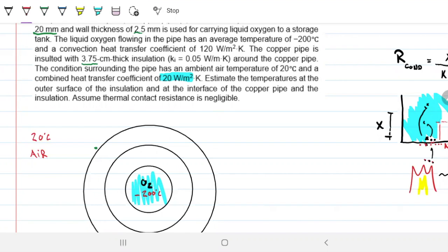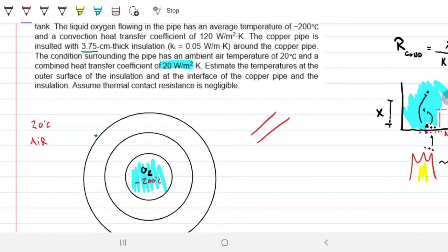Before I do anything else, I can be sure of the direction in which heat will be flowing through this pipe. We have a little pipe, and there's oxygen inside, it's flowing somewhere, and we know there will be energy going in or out through the surface area of that pipe. And what we know is it's going to go from hot to cold every single time. We have no doubt about that. It's not debatable. So we know that Q is going inside, toward the oxygen.